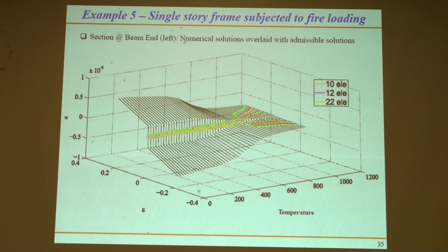Now, with fire, at elevated temperatures, we're going to have a third variable, temperature. And so you start seeing very clearly how your model changes. What's in black now is what's imposed in OpenSees. And you see that as you increase the temperature, this point here gives you the yield strength, and the yield strength is reducing, right? You don't see it as much in the Young's modulus, but you see very clearly that your yield strength is reducing.